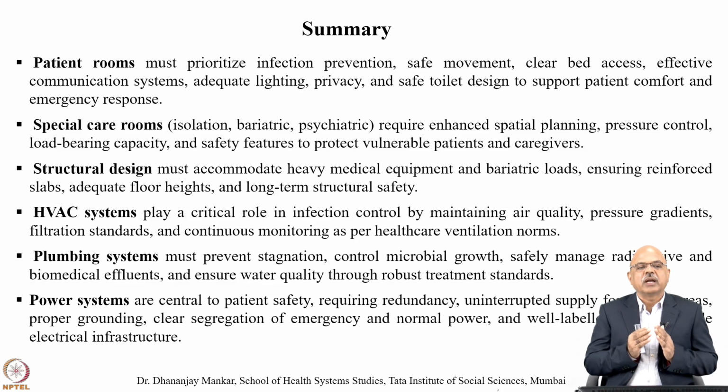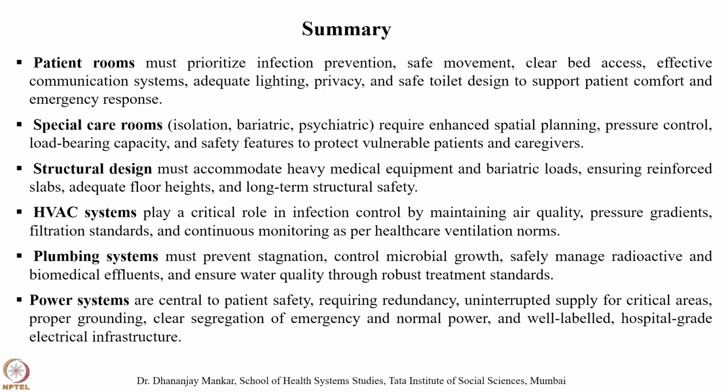With respect to structural design, we have discussed in this chapter how it emphasizes accommodating heavy medical equipment and bariatric loads, ensuring reinforced slabs, adequate floor heights and long-term structural safety. The HVAC system is identified to play a critical role in infection control by maintaining air quality, pressure gradients, filtration standards and continuous monitoring as per healthcare ventilation norms. Plumbing and power systems are also discussed with respect to controlling microbial growth and ensuring safety with respect to radioactive and biomedical influence.